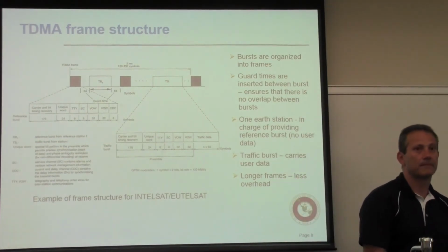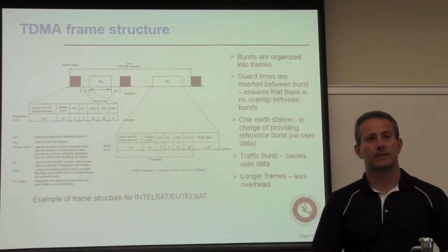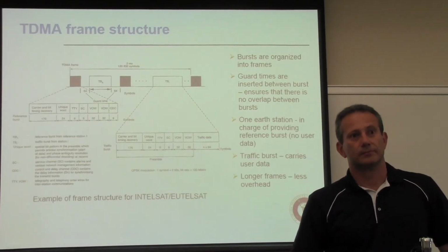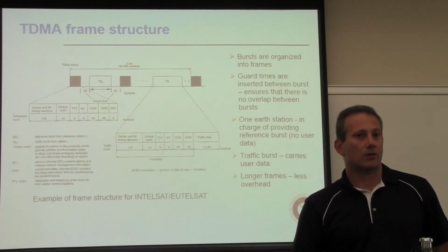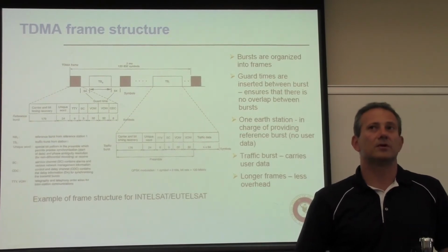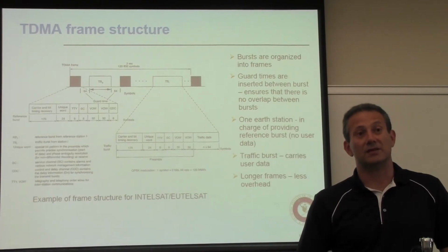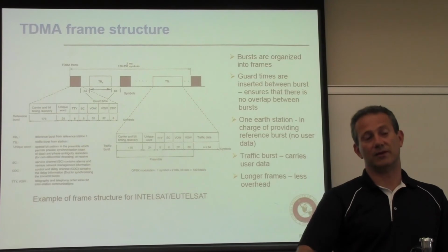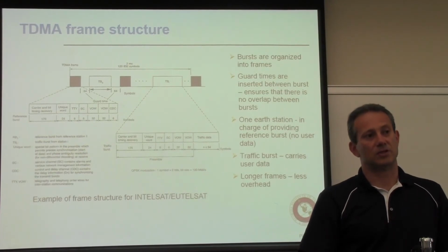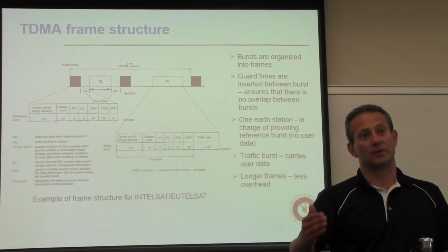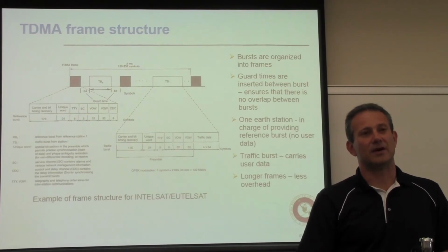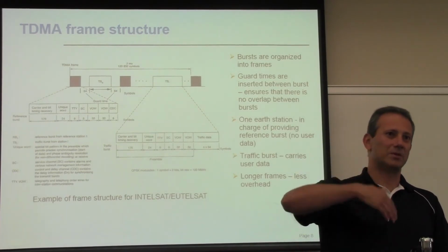So, sir, that looks exactly like the broadcasting channel in cellular communications. It's the same purpose, right? Yeah, the same purpose. If you remember, in a personal communication system, we call this time advance. In GSM, you have the ability to advance up to 64 symbols. Time advance or time offset? Time advance, because you're compensating for delay.